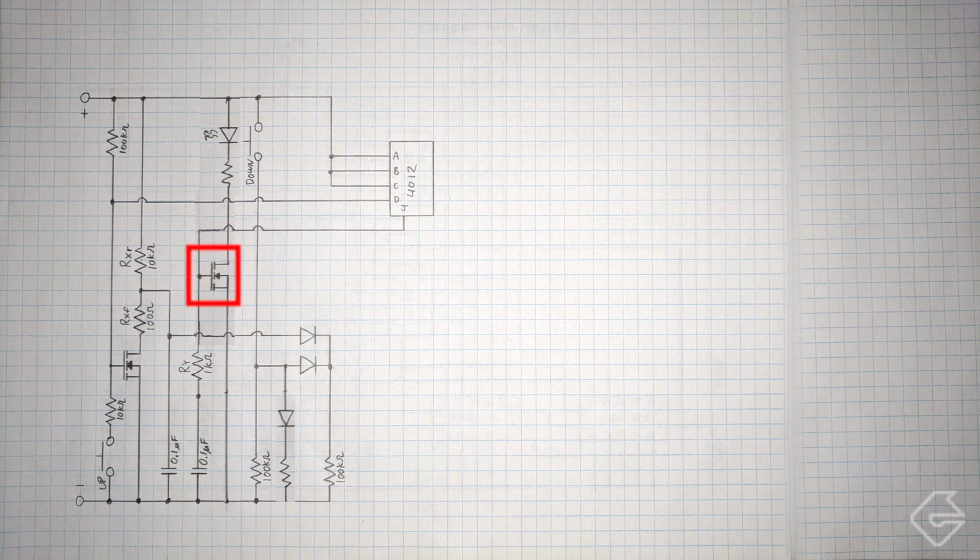And that MOSFET you can see over here. So I've tied it into the output of our CMOS output over here, and that MOSFET basically turns on the LED whenever the button is pressed, and when the button is released, it turns off the LED. And of course, we can use a resistor of any value over here in order to get a good brightness. In fact, I think in our circuit, I used a 1 kilo ohm resistor, which gives us a nice bright LED whenever we either push the down or the up button.